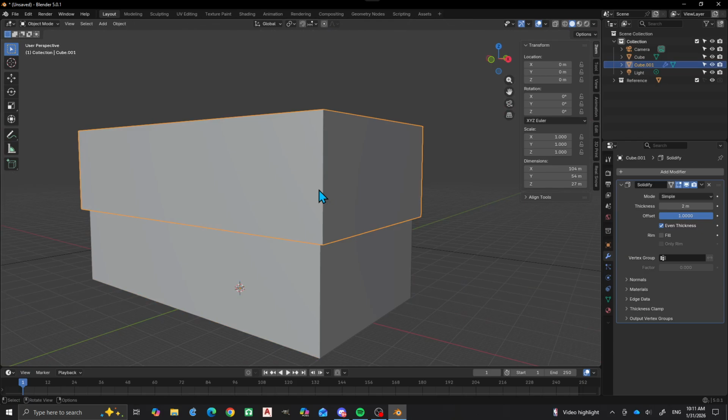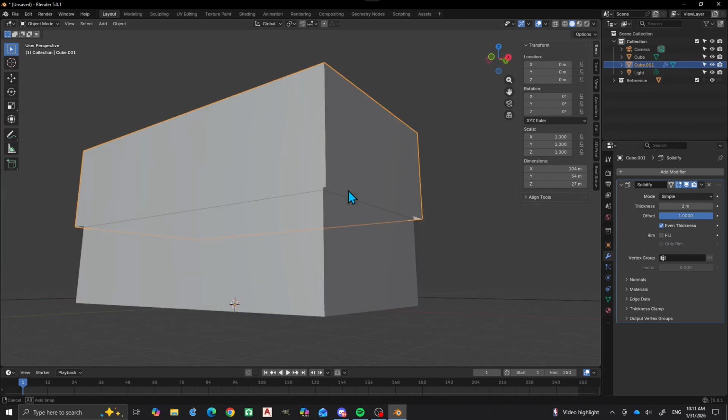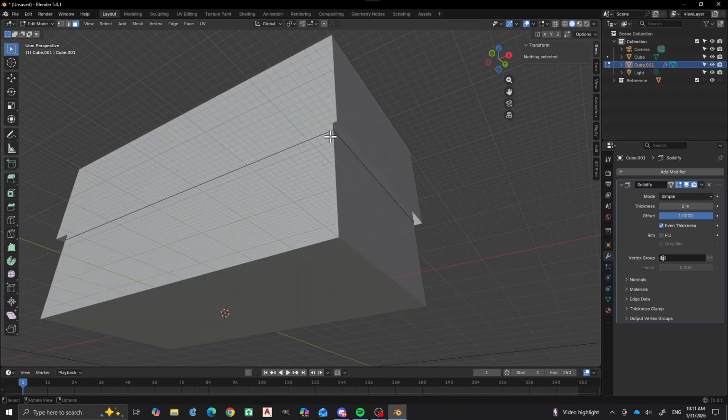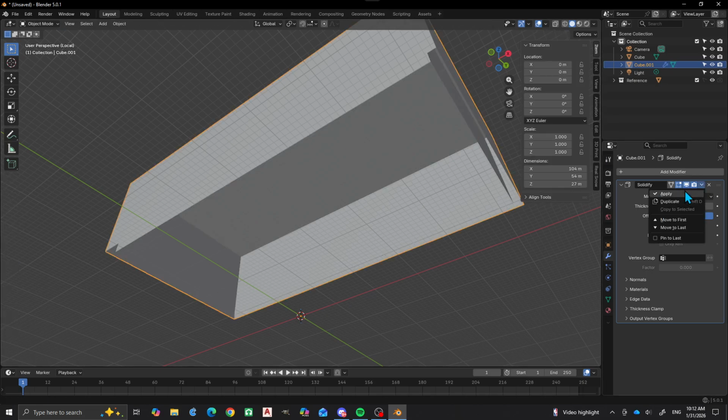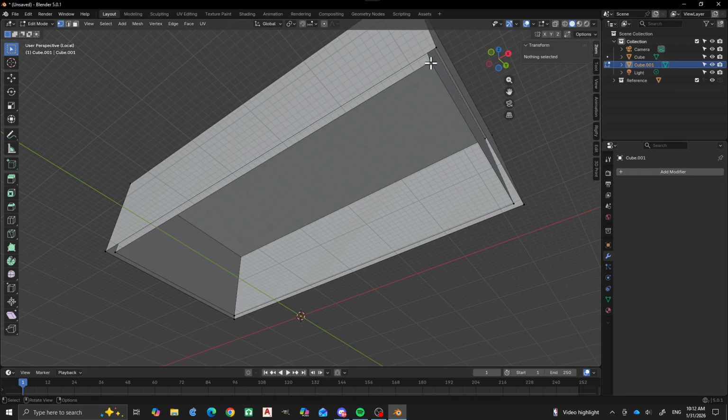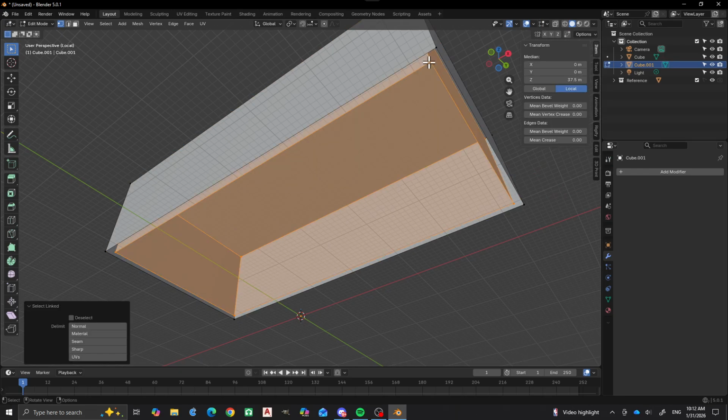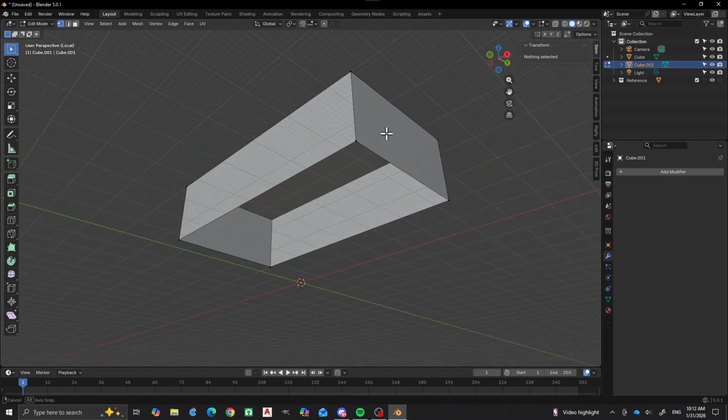Okay, so now I said I was going to take off fill and put even thickness. Okay, so now I'm going to go into here. I'm going to press the slash key so that I can get just this local here, right? So now I want to take all these faces, all these vertices in this inner one after I apply. So I need to tab out of edit mode. Okay, now we're going to apply. Now I'm going to hover over this vertex, L, X, vertices, okay?